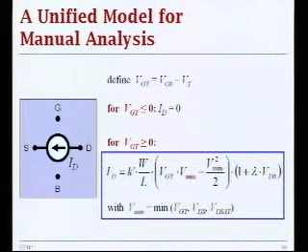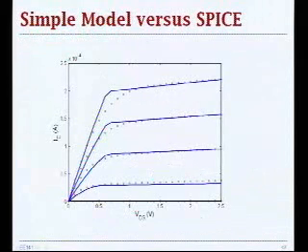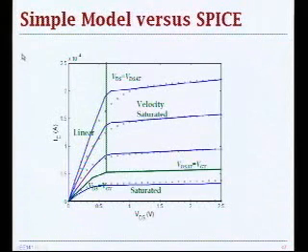And you also have this channel length modulation effect over here. Now the question is, okay, this is just a simplified model, how accurate is it? You can calibrate that using SPICE, where the blue lines are the model and these circles are the result of SPICE simulation. Of course, there is some discrepancy between the two results, but what's really important is that this model is valid in regions of operation that we really care about.